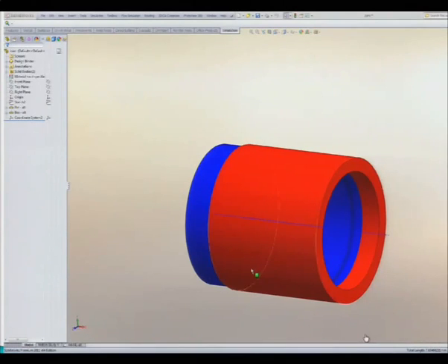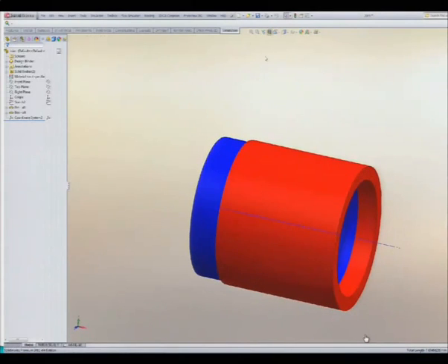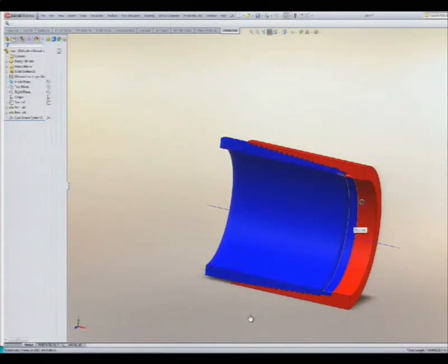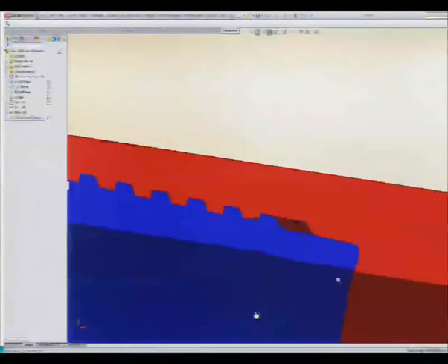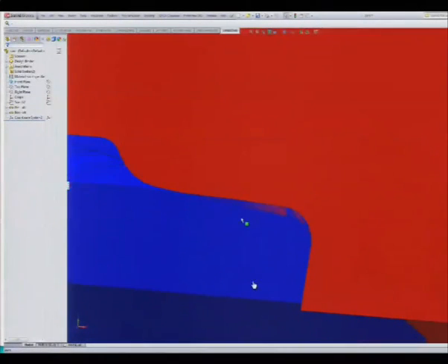Now I show you how to set up the axisymmetric analysis. Now I'm cutting only the geometrical model. You see, this is the penetration between the pin and the box. The penetration is so high, so I will have contact stresses and I will have plastic strain. So this is the challenge, to solve this at the same time.